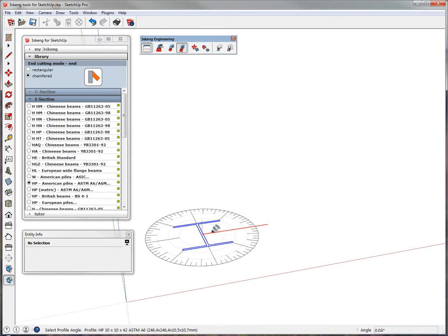The scale you see now is done in a way that the inner circle allows you 90-degree rotation. One circle further outside allows you 45s. One more, 15 degrees. The outer circle, 5 degrees. And if you are outside, you can freely choose the rotation. In this case, we just stick with the standard one.